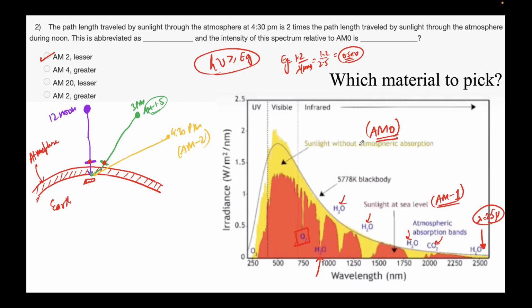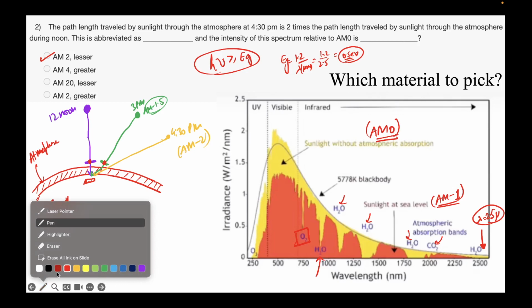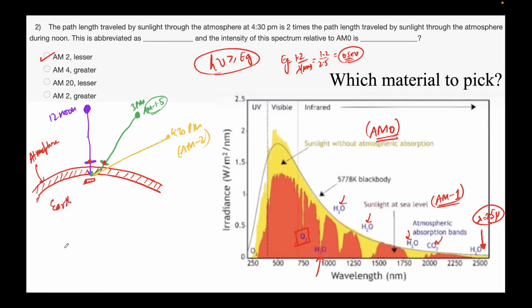This does not always work the best, but essentially, let's say I choose silicon as my material. Let's say this is where silicon lies. Silicon's band gap is 1.1 eV, right? Correspondingly, the wavelength lambda will simply be 1.2 divided by 1.1, so it's coming out to be about 1.1 microns. Okay, so 1.1 microns means somewhere over here. So this is lambda silicon.